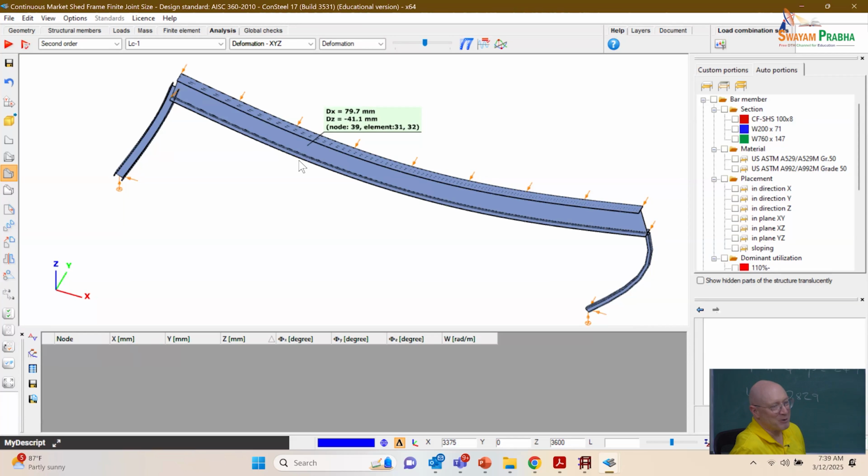We could use a larger HSS column. If we go there and we start doing that, what's going to happen is that this is the type of problem where we make the HSS column bigger, it attracts more moment, and the unity check gets larger until it gets big enough where it's not a problem. Now, clearly, if we had wide flange sections that were equal on both ends of the frame, then life would be good, right?